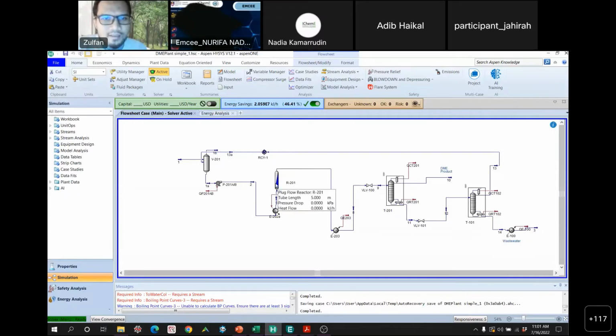And this reactor requires a pressure of about 15-16 bars and a temperature of about 250 degrees C. So as a base case, I just put a dummy case, so assume that this is your plant. We have room temperature methanol, and we want to heat that up to 250 degrees C, and this is the amount of energy that you will need, about 4.4 megawatts.